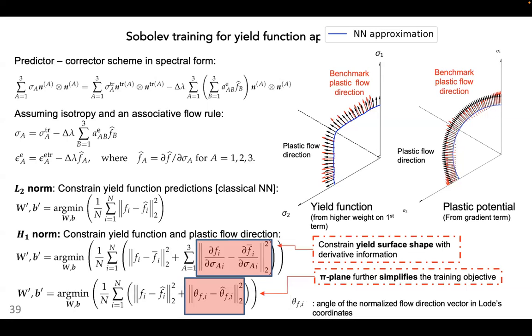If not, then that means you may want to introduce another change on the plastic flow. And the plastic flow I will recommend is the following. I could find a case where the yield surface looks like that, but the plastic flow is more smooth. I don't know why for the microstructure, but the important thing is the following.